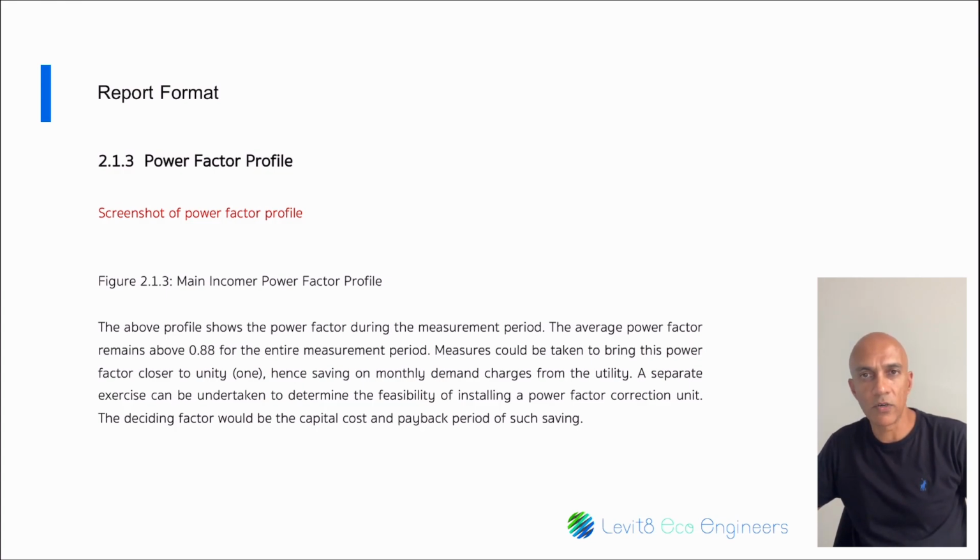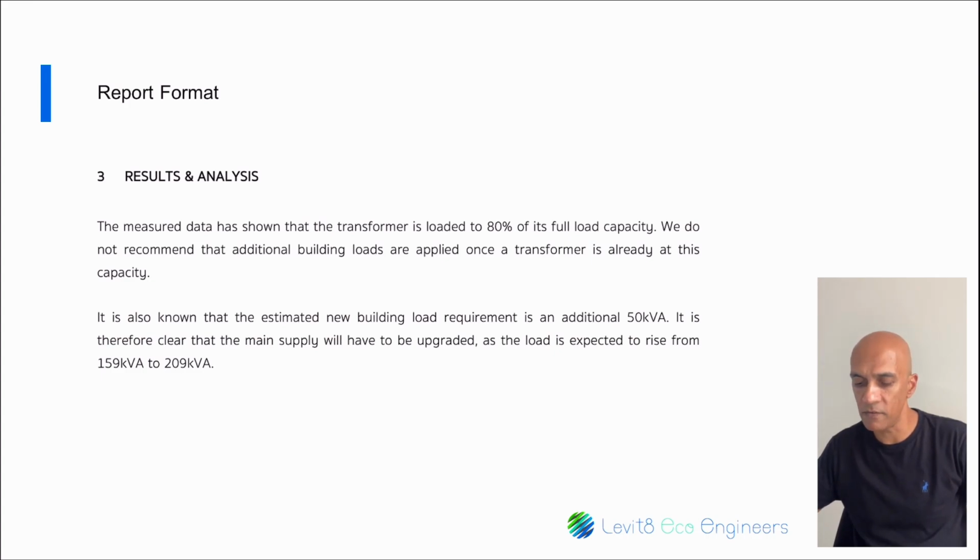Then you have your power factor profile. And here you're basically going to talk about your power factor during various times, or your average power factor. This may only be relevant if you're looking at doing power factor correction, or highlighting to the client that there is in fact a very poor power factor at the facility.